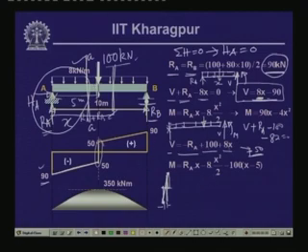And then if we compute the value of shear force at this end, where x is equal to 10 meter, in this particular expression if we substitute the value of x as 10 meter, then 8 times x is 80, so 180 minus 90, so this gives us a value of 90, which is the shear force at this end. So, it again varies linearly and comes down to this place.